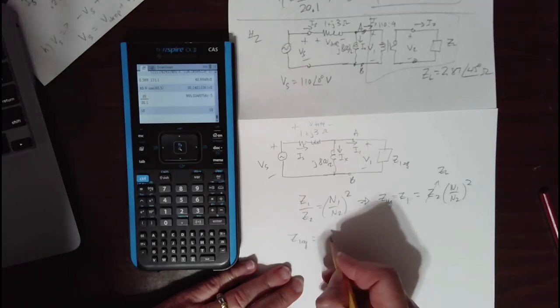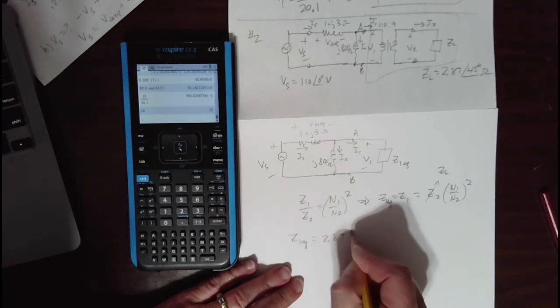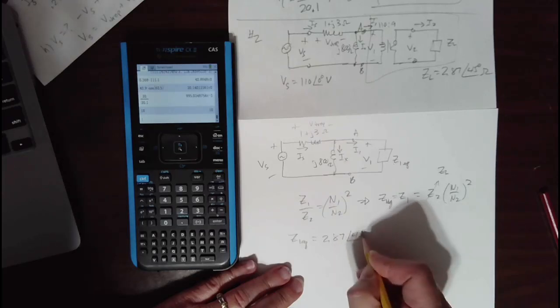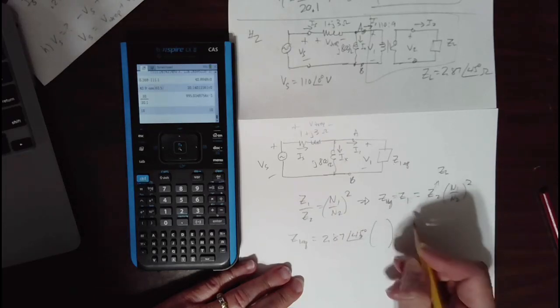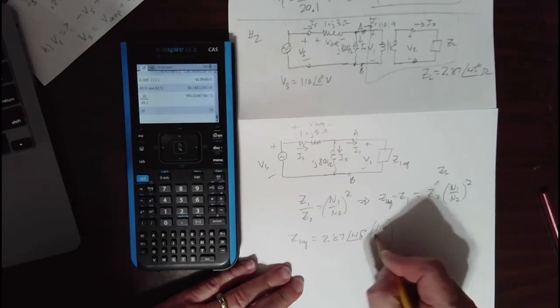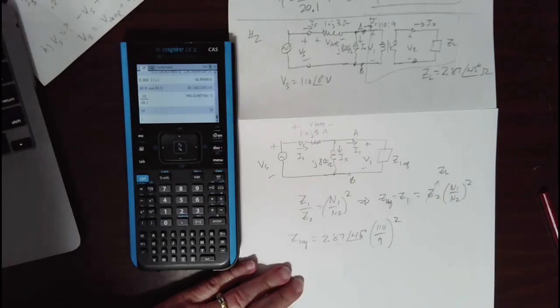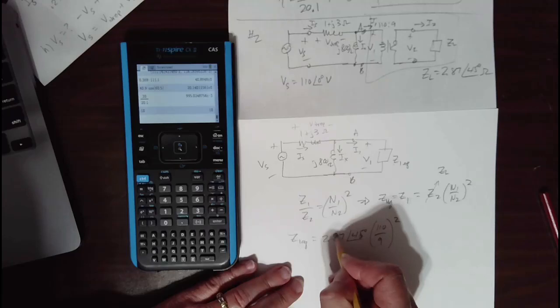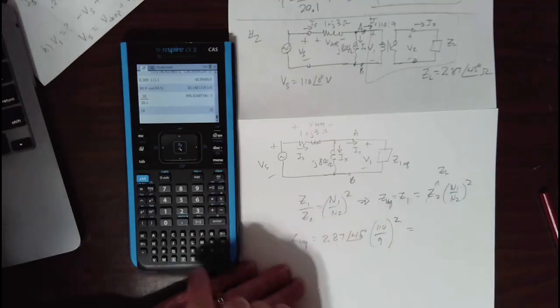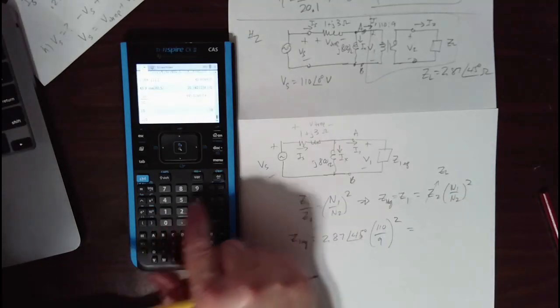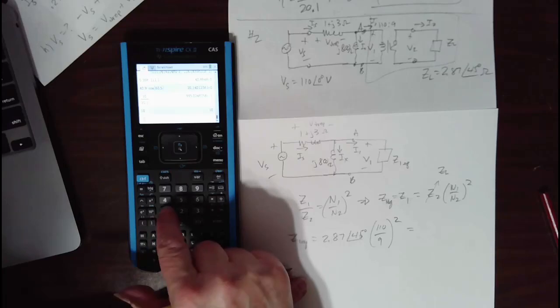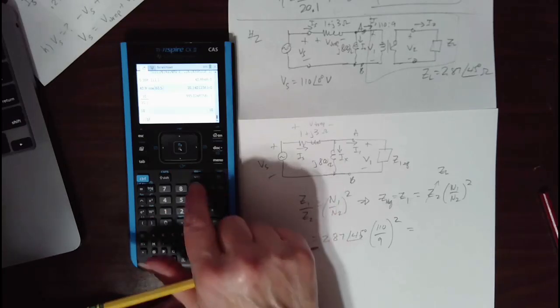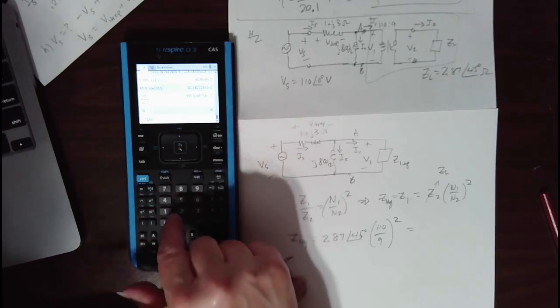And so Z load is 2.87 angle 45 degrees times N1, 110, over N2, 9, squared. Again, this is just a real number. It's just going to change the magnitude. The angle is still going to be 45 degrees. So we're going to have 110, let's put this in parentheses, 110 divided by 9 squared